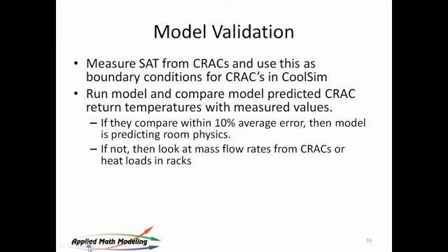A probe under the floor in a raised floor case, and measure what the cold air temp is. You also want to measure the return temp at that same point, because we're doing an instantaneous point here. We're looking at it at one point in time. To be honest, the supply air temp varies depending on whether the compressor is on or off. But if you take a snapshot in time and then build a model based on the snapshot and validate your data, at least you know that the physics are being captured by the model.